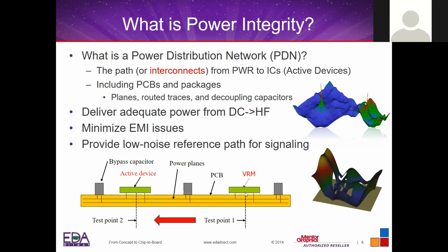Okay. In addition to that, you have some side benefits from the PDN. For example, given the plane structures and the plane size, it will be able to shield the magnetic radiation coming from the trace switching. You remember the right hand rule? If the current is flowing this way, the magnetic field is flowing around the trace. So that magnetic field will radiate, and the power plane will be able to shield or contain that type of radiation, which can cause crosstalk issues and EMI type of issues.